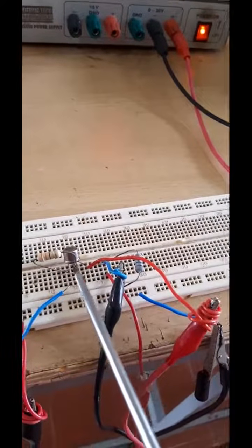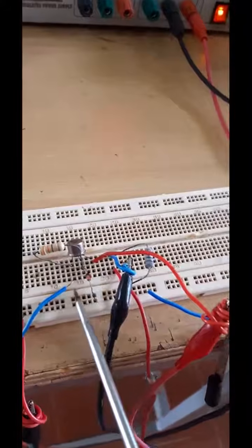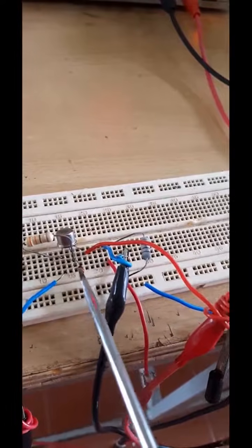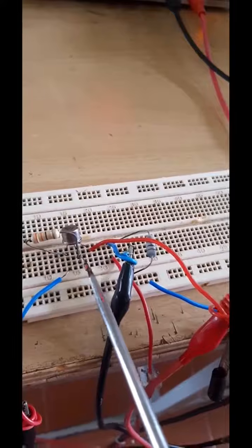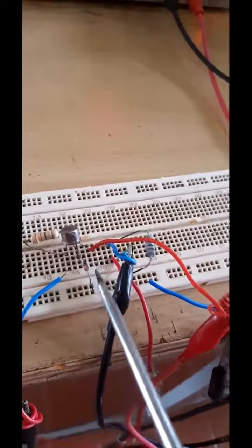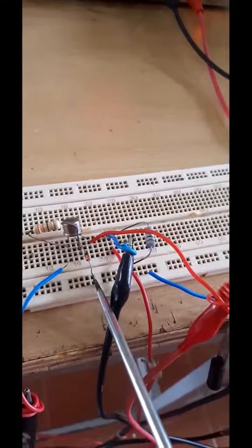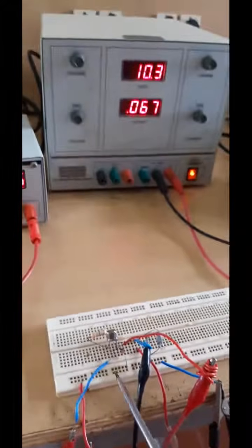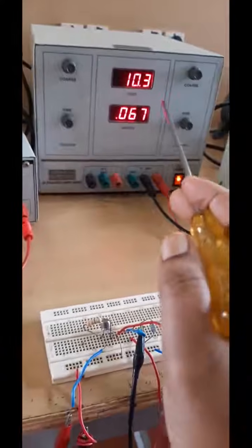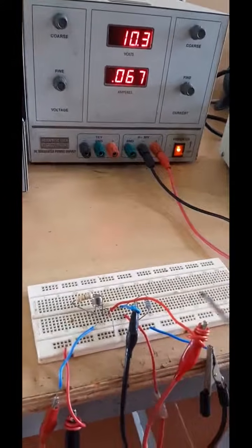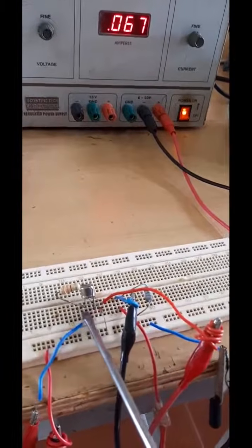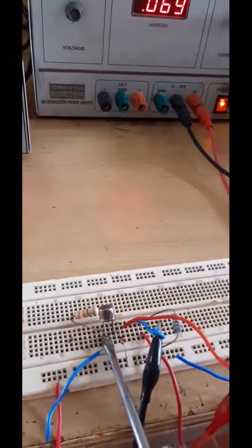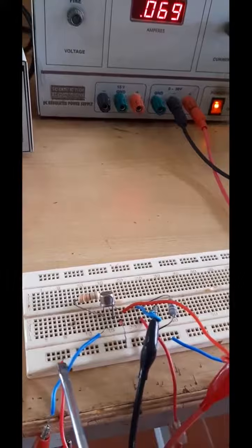And next is the Zener diode. The Zener diode is connected at the base of the SL100. You can see this is the Zener diode, and the negative of the Zener diode has a black mark. You can see here the black ring, and negative is connected to this point, and positive is connected to the ground point. And we need a voltage source from 8 to 12 volt. The voltage source positive is connected to this resistance terminal, that means it is connected to the collector terminal of this transistor, and the negative is connected to the ground.